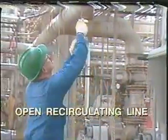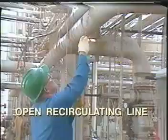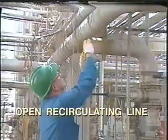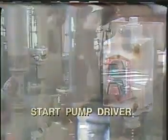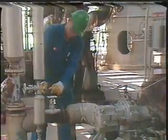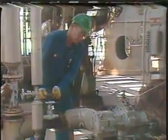Some pumps are equipped with a recirculating line that recirculates liquid from the discharge back into the suction line. The circulating line should be opened before the driver is started to prevent operating the pump against dead shutoff. Now start the motor. Or, if the pump is driven by a steam turbine, start the turbine following standard practice recommended by the manufacturer and your operating instructions and procedures.